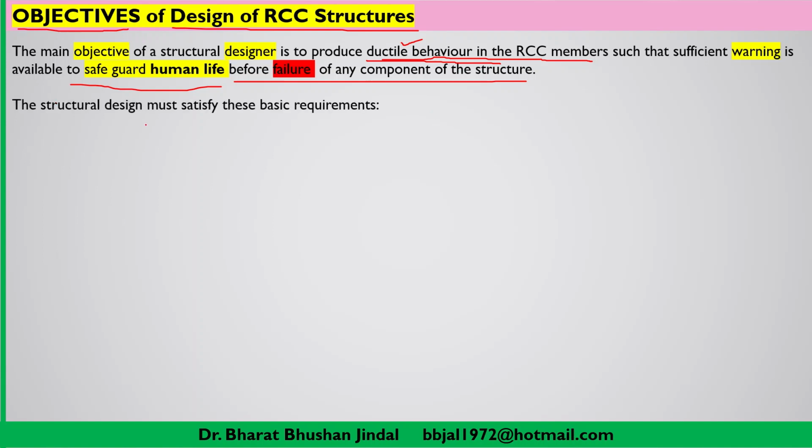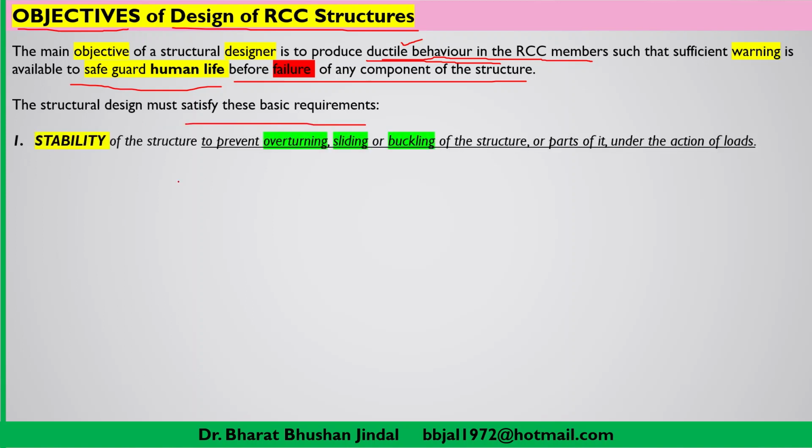Now, structural design must satisfy some basic requirements. Very first is stability. Your structure must be stable. Stable means any type of overturning, sliding or buckling of the structure or any part of it under the action of load should be prevented.